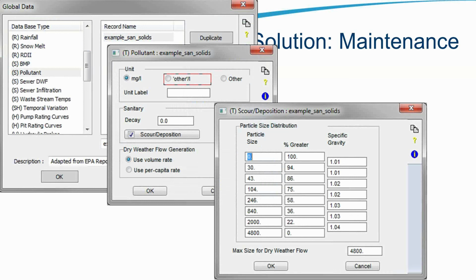So that area that's maybe a 0.5% slope, you can see what happens. If we do some routing and move the flow so there's less flow there, now maybe the velocity gets even lower, now maybe we have problems. Or perhaps you're routing a sludge return line, something that might have a higher than average solids percent. That's something that you can model and get an answer on more than just the rule of thumb answer or the estimate answer. That's one idea of maintenance.